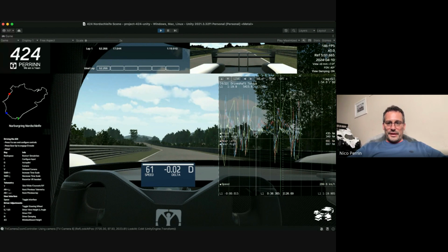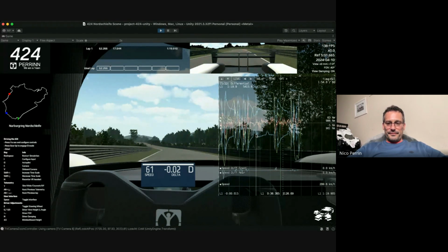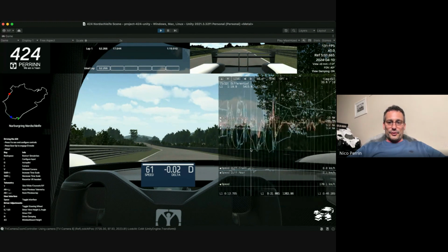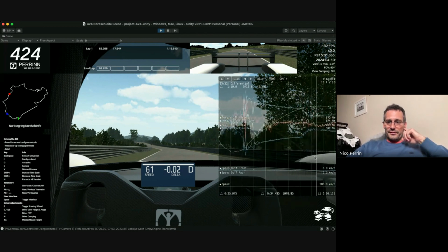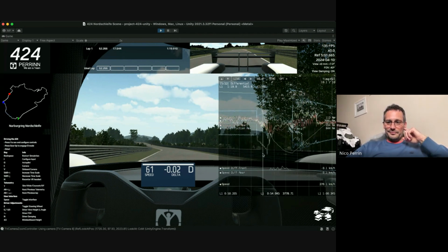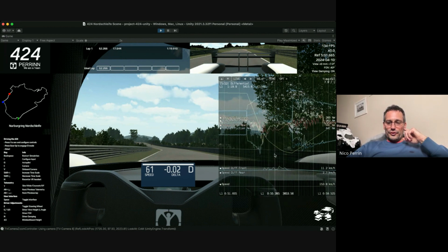The other thing I can show you quickly using the telemetry: I talked about the differential, and I want to talk to you a bit more about it here. Let's go back to that long corner that I like. It's a bit difficult to see here, but there's an interesting channel, which is the differential in the transmission, front and rear. And it's extremely important to the balance of the car. I talked to you about how the diff was opening towards the late entry and very closed. You can see it here on this channel.